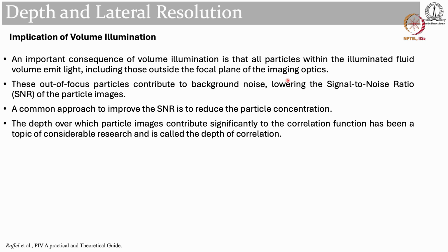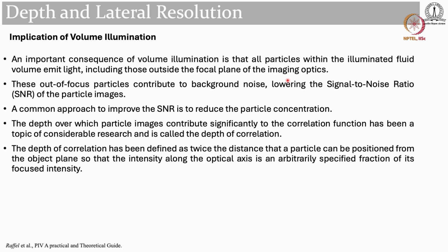Now how do you define this thing? There are a lot of definitions you can find in the literature, but one of them is that the depth of correlation is defined as twice the distance that a particle can be positioned from the object plane, so that the intensity along the optical axis is an arbitrarily specified fraction of its focused intensity.